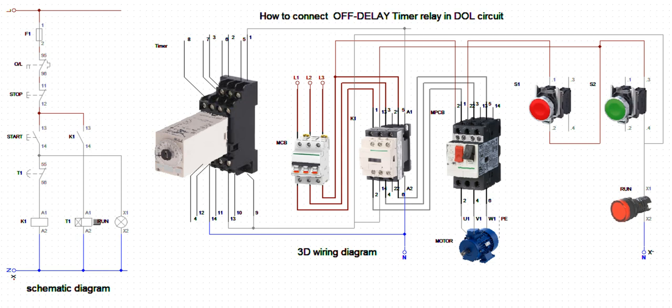Okay, so let's test once more. I put the system on. This one is energized. This one is on. This one is timing. After 5 seconds, look at it shut down. So this is how to incorporate off delay to your DOL circuit. Okay. All right. Thank you.